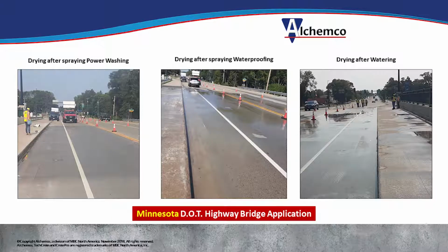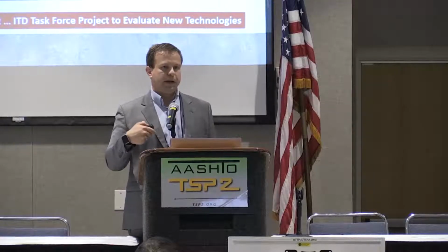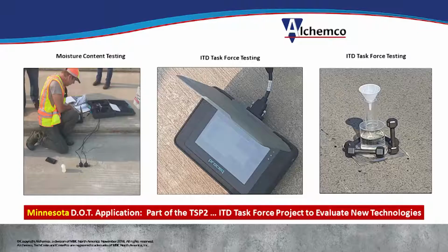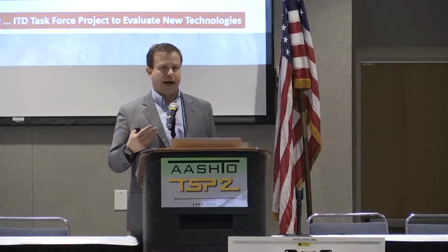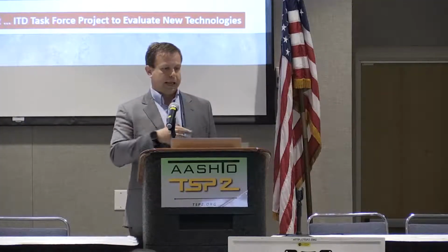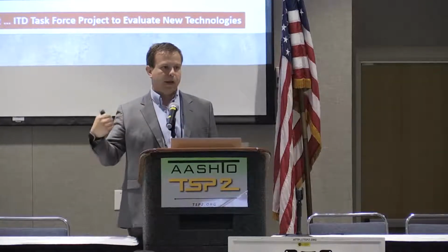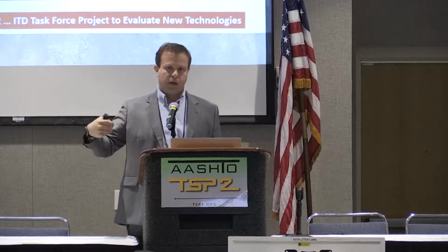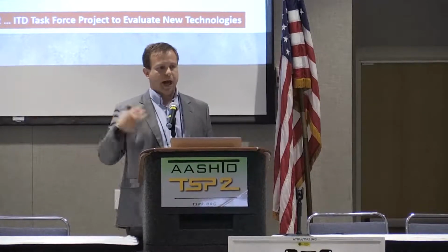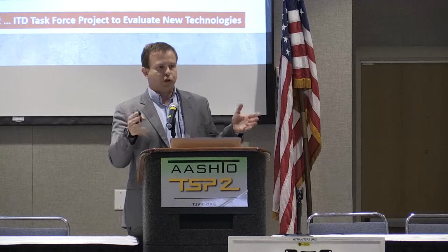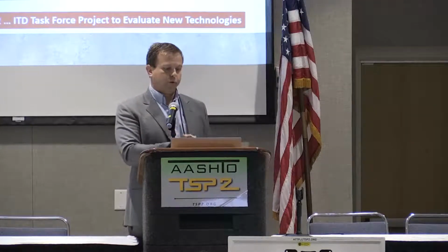Minnesota, this is one of the pictures from the report that we did for the ITD, where they measured the water penetration on the concrete and the water penetration when there were cracks. They also measured the chloride ion before the application. And for the ITD program, the next test is going to be 1 year after the application, and then 3 years, 5 years, and then 10 years after the application, exactly to be able to show the long-term benefits of this technology.